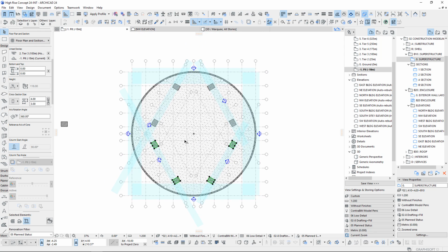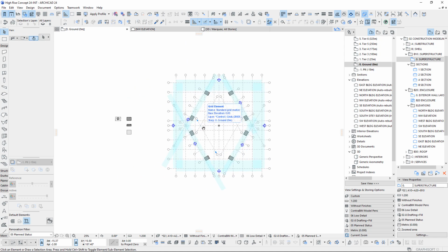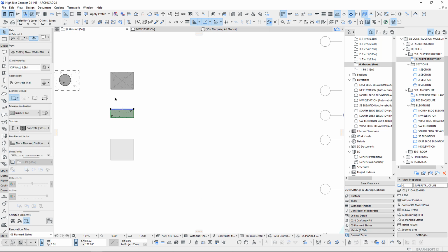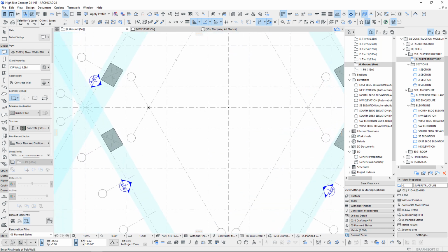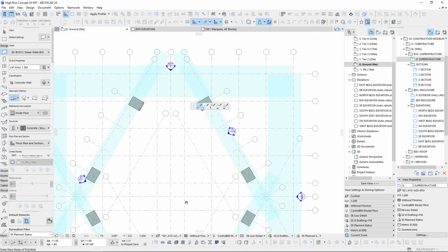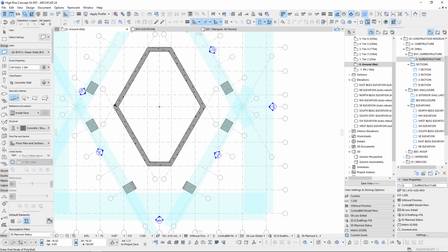All right, there we go. And let's also get our core in here as well. I think I have the shear wall up here on our first floor level. Let's pick this up. We can input it from here. That's fine. So we'll just take it from this point, snap it out to there, to there, to there, and down. So we'll get our core walls in.